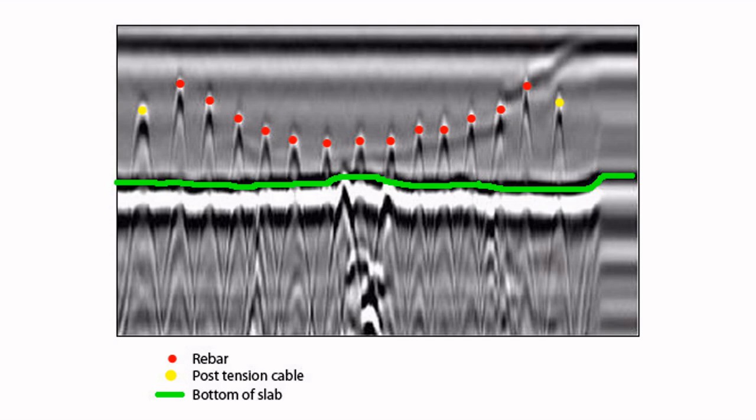If we are drilling a hole and there is a rebar, then the drilling may be tough, it causes damage to the bit, and it will also take a lot of time to reconstruct the rebar. And if there are post tension cables, those cables will be disconnected and again we need to do a lot of work.